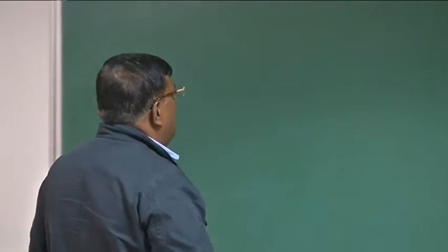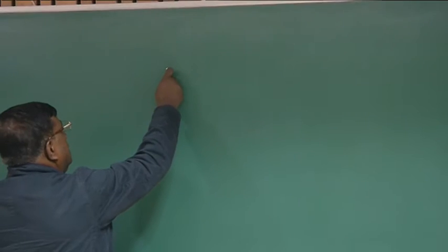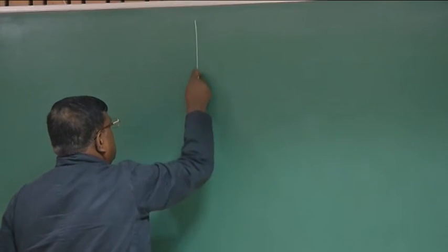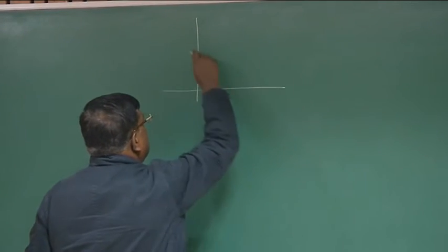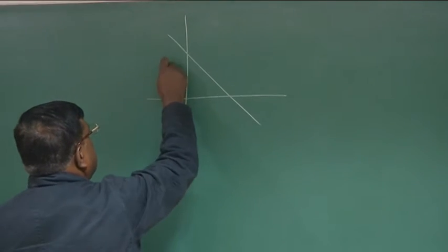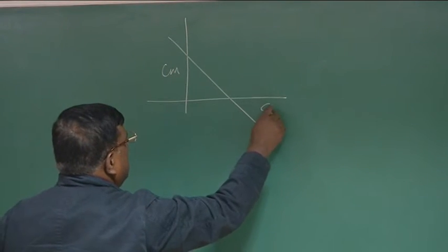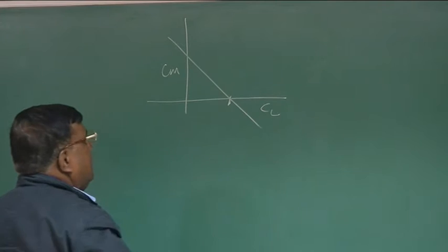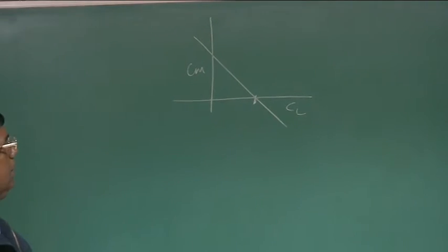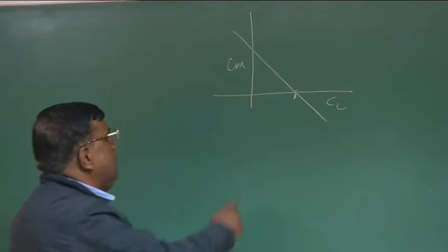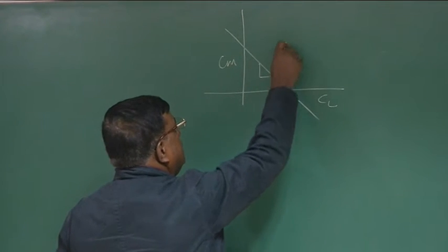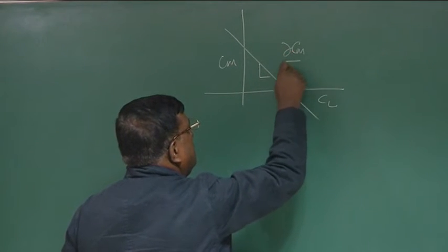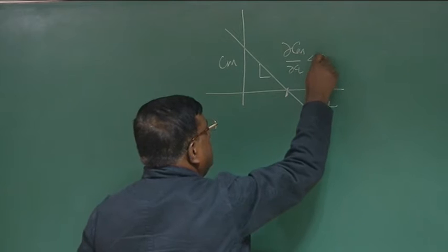If you recall how we started, we understood that if an aircraft is statically stable and it can be trimmed at a positive CL or positive alpha, then I need to ensure dCm by dCl is less than 0.